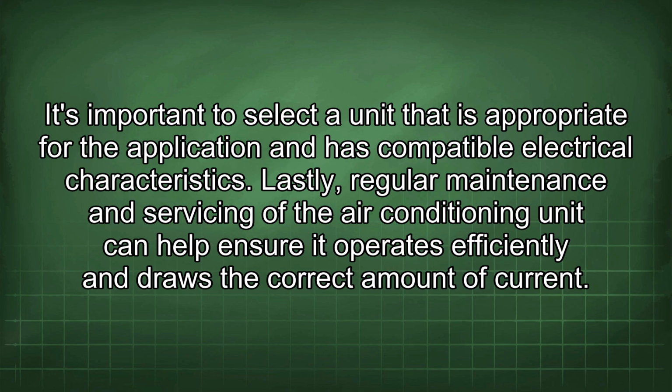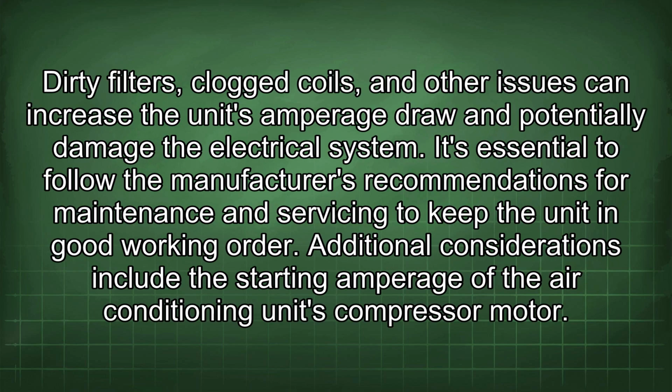Lastly, regular maintenance and servicing of the air conditioning unit can help ensure it operates efficiently and draws the correct amount of current. Dirty filters, clogged coils, and other issues can increase the unit's amperage draw and potentially damage the electrical system.